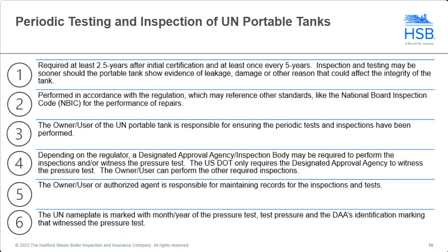Periodic testing and inspection of UN portable tanks. So we just covered that it's certified, and now it's placed in service. 2.5 years after that initial certification, it's required to have a periodic inspection and test. And after that, it's every 5 years.